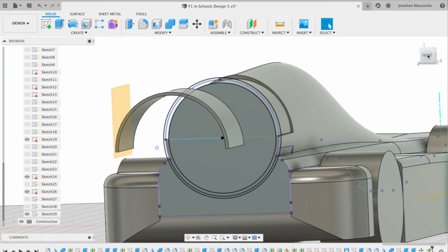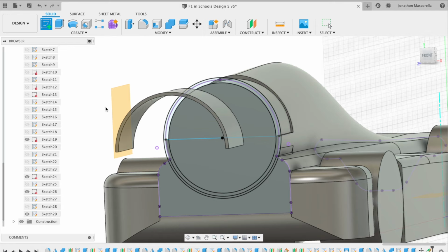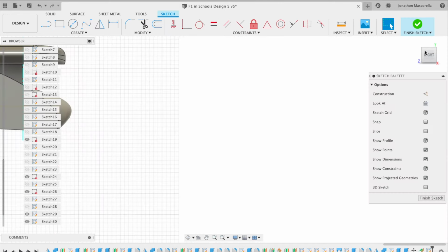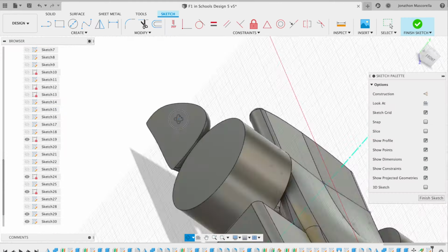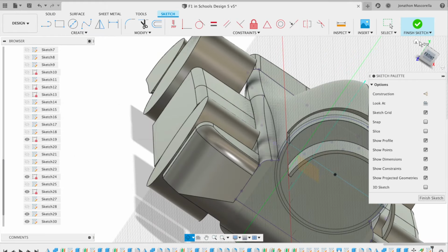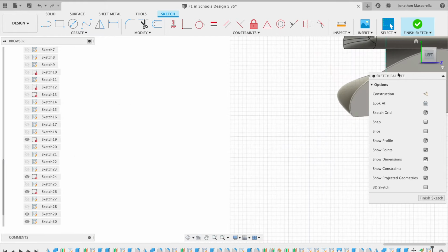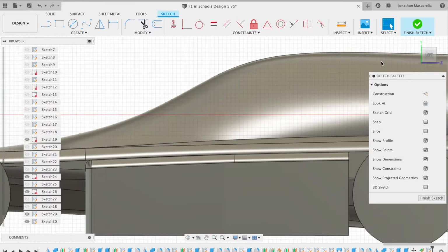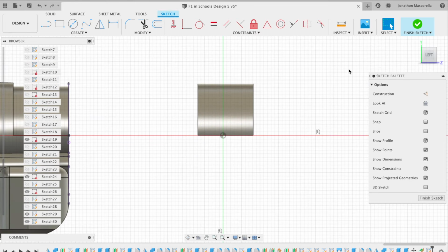I suppose there's two problems with leaving 3mm around the CO2 canister at the beginning of the design, and that is that then basically you'll find it very challenging to sand the rear of the vehicle and get it looking perfect, because you won't have any variance if things go wrong, and if you're under 3mm it can be a disqualification. So just be cautious of that. But I'll let you watch as I go through the design of the rear wing.